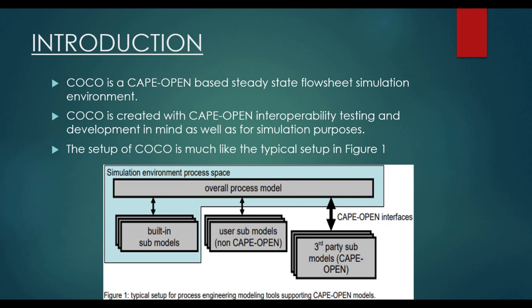But when we talk about the dynamic state, there is an accumulation term which is with respect to the time. So you see the flow rate which is entering into the equipment and after being processed and becoming a product, you consider the time in the dynamic state. So that's the basic difference between the steady state and dynamic state. So this software is a steady state based flowsheet simulation, and it's COCO, it's CAPE open, and